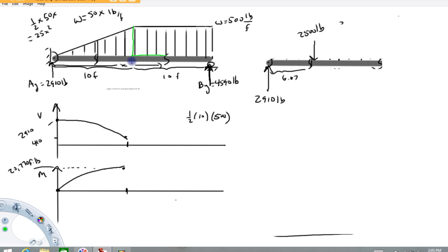That second distance I just drew, that's 500. That's no problem. 500 pounds per foot. This distance is equal to x from here to here, x minus from here to here, 10. So x minus 10 times 500 is going to give that force vector. I'll go ahead and leave those there. And that force is going to go at the centroid of this rectangle.